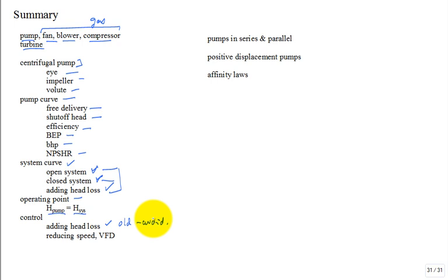Lots of places. So as a young engineer, you may be tasked with energy efficiency. You may want to go looking for some of these things. Equipment that's not running right. Or things where you ask, hey, why is this valve partially closed? It's always been that way. Well, let's strip it out, open it up, and put a VFD somewhere in the system and toggle down the speed.